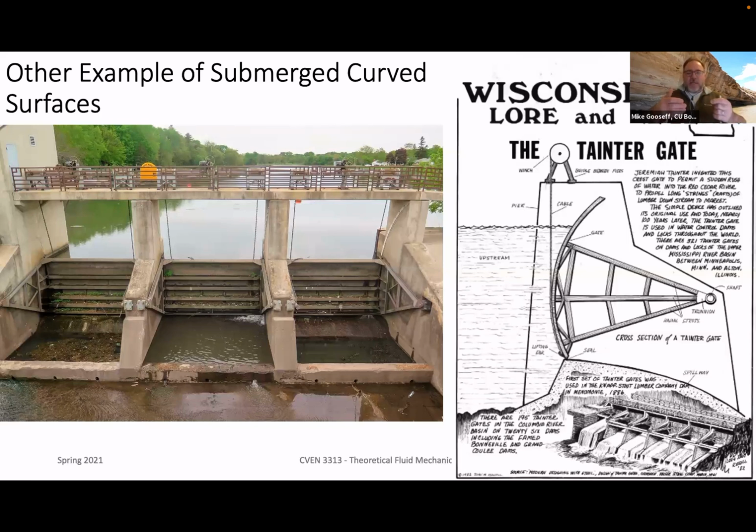The way these work is they're rounded. You can see the picture on the right, a cross section of the way they look, and we'll work a problem like this later today in class. You try to lift this up, so you're basically allowing water to move out the bottom rather than go over the top. When you do that, you can trap all of the debris up here, and it doesn't have to affect your hydraulics.